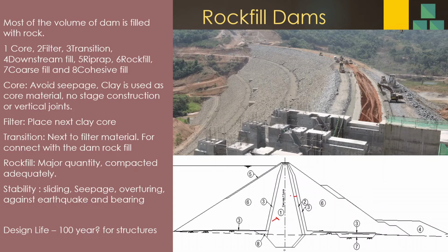Most of the time, actually always, you have a filter in dams, to send the water out smoothly without eroding the clay core material. If you don't have a filter there, the clay in the dam will be washed out. Therefore, you have to have a filter there.